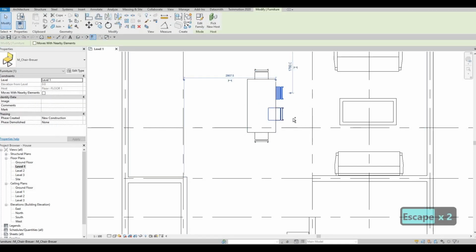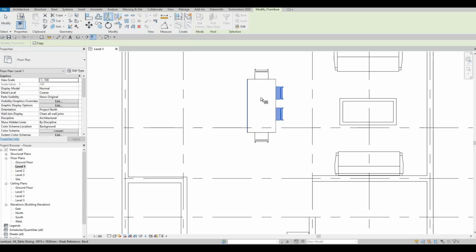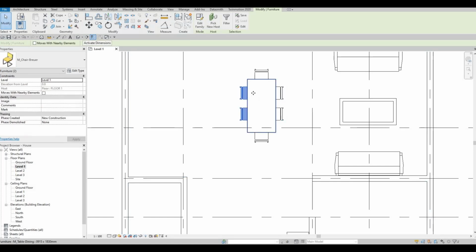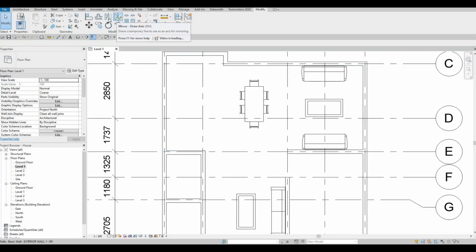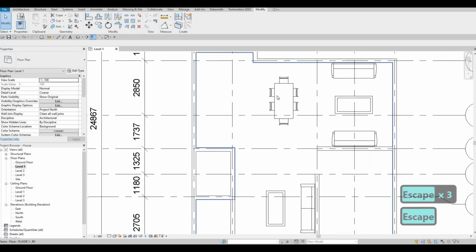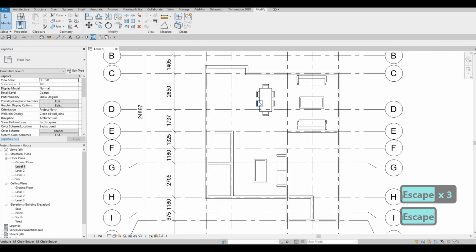So hold on Control and then select this one as well, and then you could use this as well because there's a midpoint showing up there, so you don't need to do the draw axis. So if you know that there's a pick axis, you'll be able to select that as well. So that one is good as well.